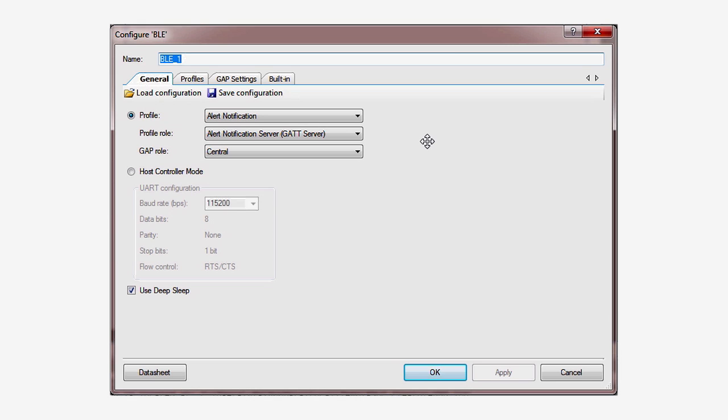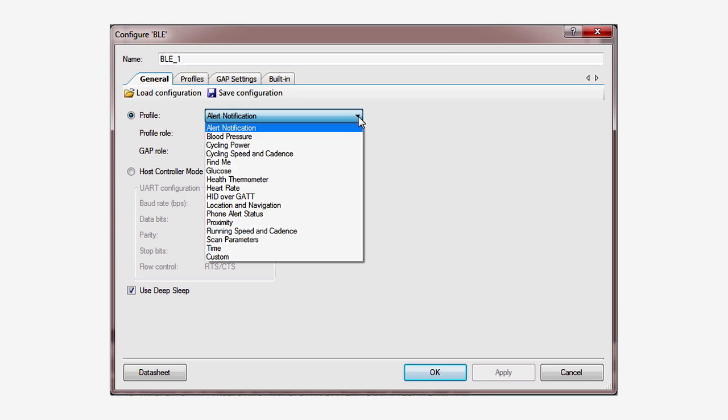All BLE devices are implemented with profiles. A profile is just the BLE word for a Bluetooth SIG specified collection of data and functionality, which are called services. Some examples of these profiles include things like heart rate monitors, bike power meters, and running speed indicators.